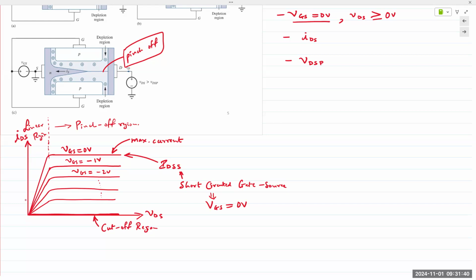So as I was saying, we have to think of it as backwards. Normally, we would say the device is cut off, but you apply a voltage and then it allows current to flow through, right? But this is a depletion mode device, meaning the channel is always on. So you apply a voltage to actually reduce the current.